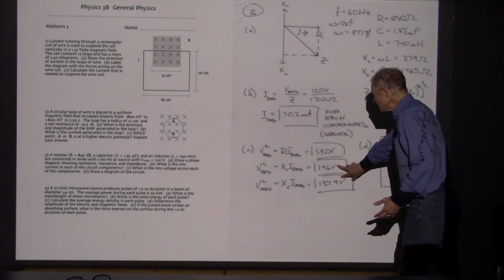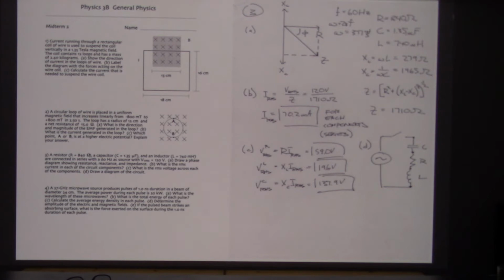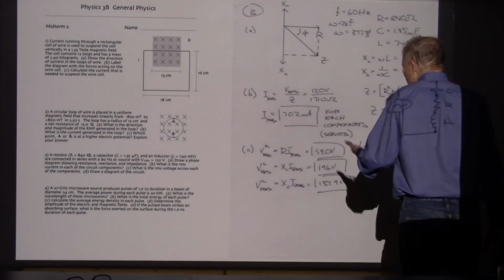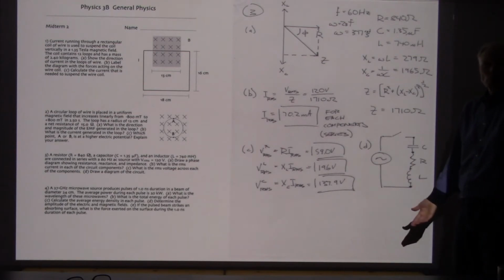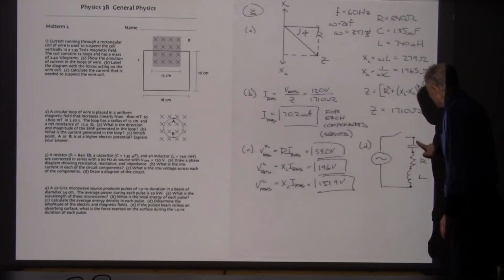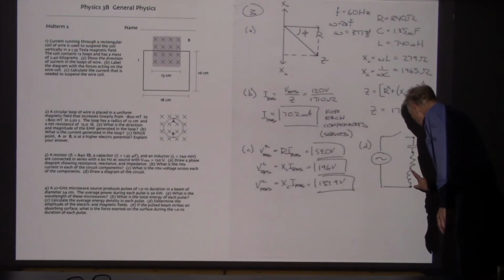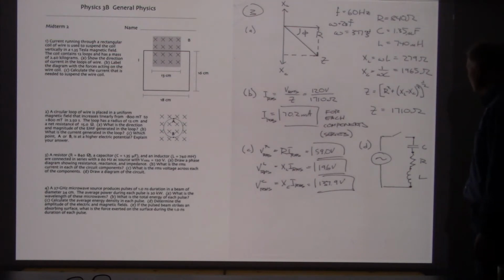These are exactly out of phase with each other, a half cycle out of phase, and so those two voltages cancel out. Now you might think, for the voltages to cancel out, do I need to have the capacitor and the inductor right next to each other? And we don't. The only requirement is that they're both in series with each other, and so whatever voltage is here at some instant will cancel with some of the voltage that's here at that same instant.